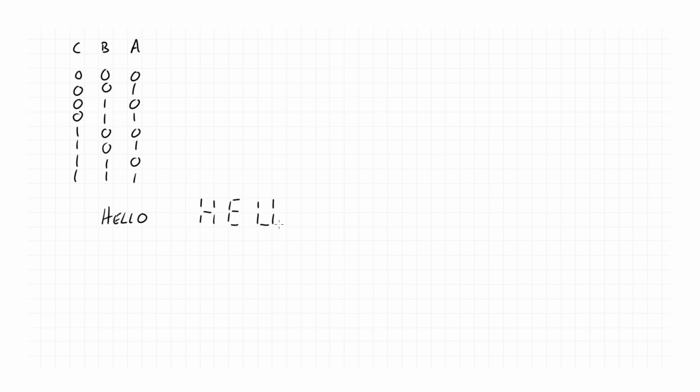So now I want to make a 5-character message, so I need 3 bits of binary count to count between 0 and 7 to say hello, like Stampy does. We're going to do H, E, L, L and O, and we're going to figure out the truth table for each of those letters. So when the counter is at 0, 0, 0, like the 0 count, I want all of my displays to be completely off. So I will put the segments at logic 0.